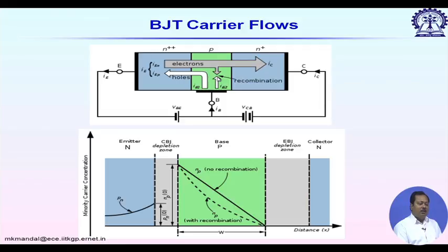That is why the conventional BJT is not used at millimeter wave frequencies. We have some other version which can take care of this reverse saturation current, and this modification is called the heterojunction bipolar transistor or HBT, that comes just after this.